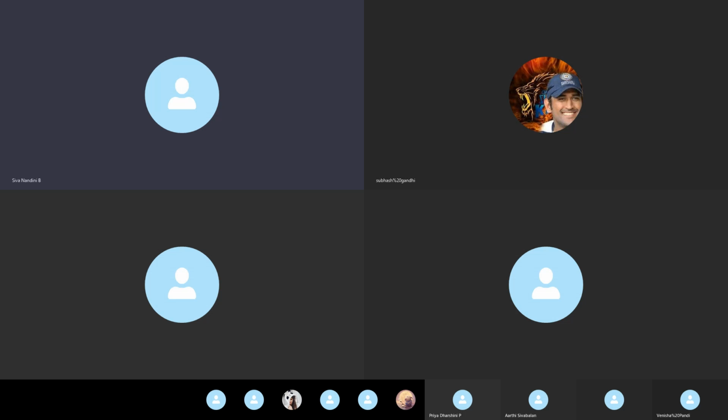In slide number 16, on the left hand side you can see the outer layer coated with photoresist. See, this is how the dry film will be covered over the outer layer. And next, after the exposure, we'll have the image as shown on the right side. That is, the outer layer will be exposed. Some portion will be exposed and it will be removed away.